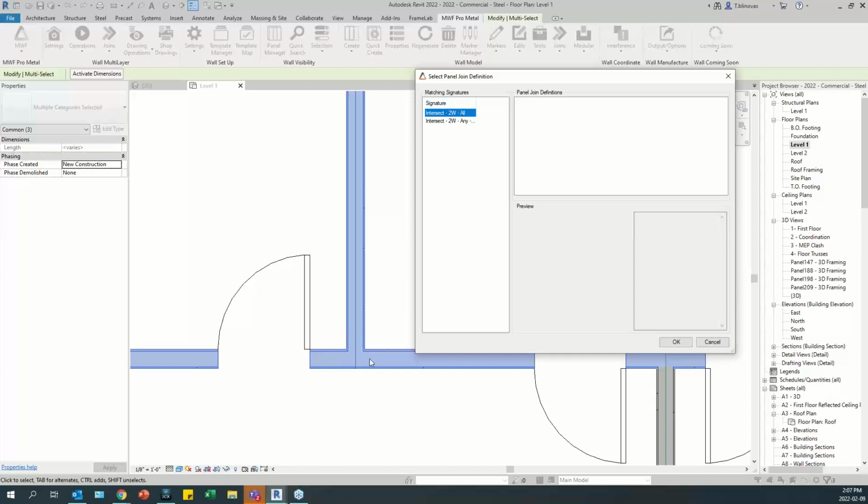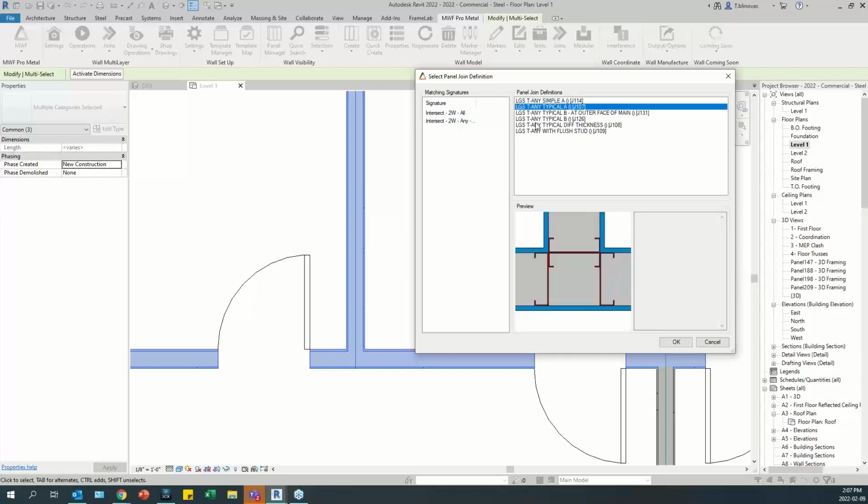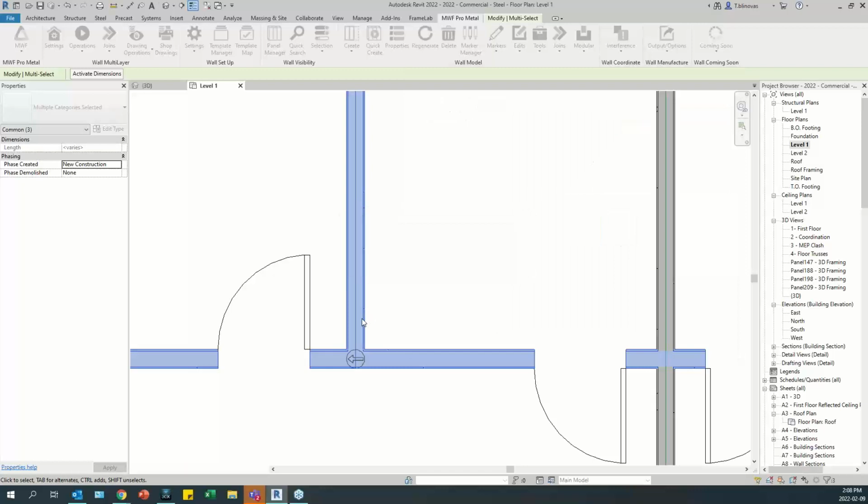So for example, the T intersection that I have here is still just 2 walls intersection. So in that case, as you can see, it does identify as 2 walls, but it sees also that it is a T intersection instead of a regular 90 degrees corner like we did. So you would pick here from the list as well which one you think is best and hit OK.